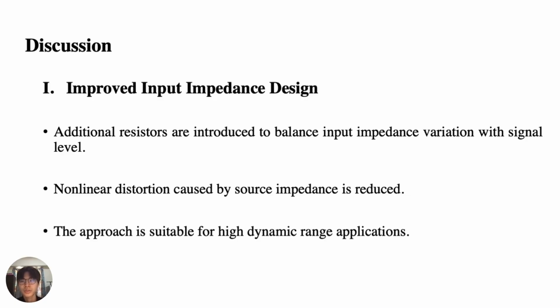In most traditional designs, the input impedance is assumed to be constant. In contrast, the input impedance of this circuit varies dynamically with the amplitude and polarity of the input signal, while remaining symmetric around the bias point.